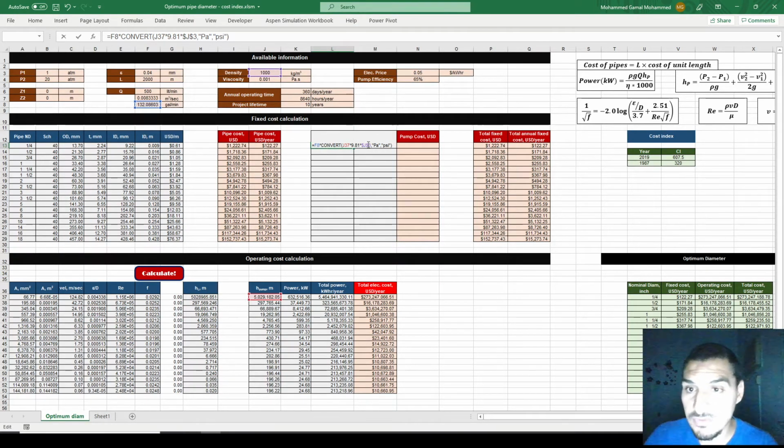So this is the flow multiplied by the head in psi, and then divide this by 1000, because the values are multiplied by 1000. I have everything here, right? So what I'm gonna do is, I think I did something wrong. Oh, the flow rate was not, I didn't press F4 here. I think something else is wrong. Oh, I clicked F4 on the wrong thing. This has to be constant. It has to be variable, and this is the constant parameter here.